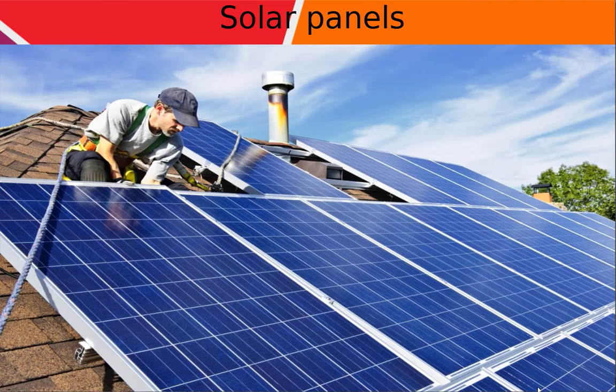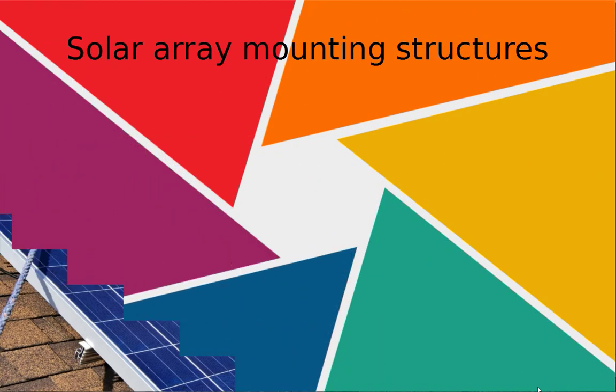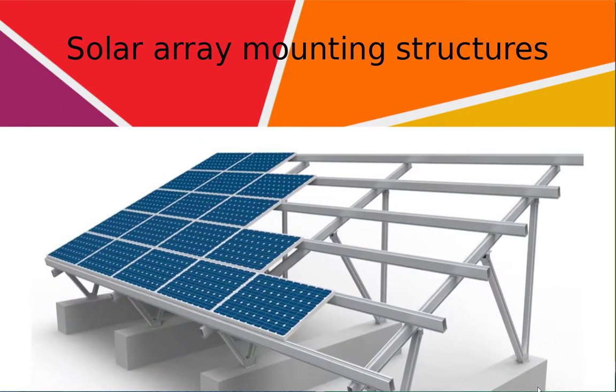Panel mounting structures. These are fixtures that hold the solar panel in place. Their appropriate design is essential to make sure the panels get maximum sunlight. The mounting structures are usually made of galvanized iron or aluminium. They have to be designed for wind loads applicable in the region. There are two types of mounting structures. The mounting structures are long-lasting and require no maintenance.